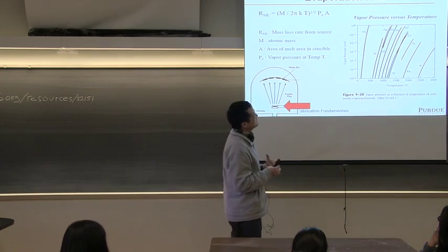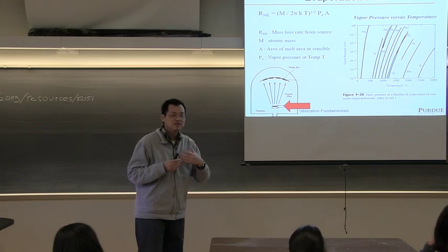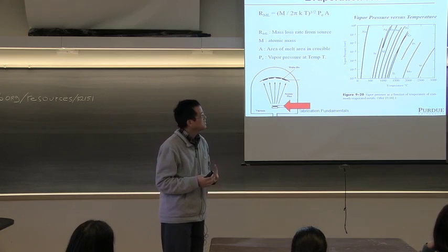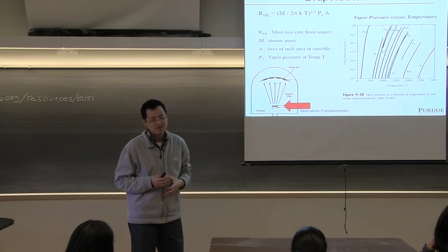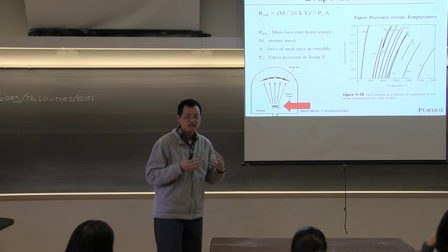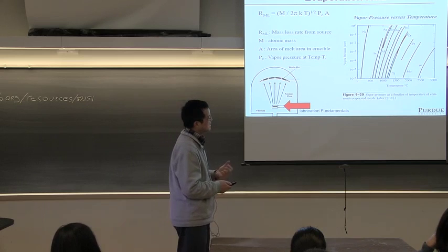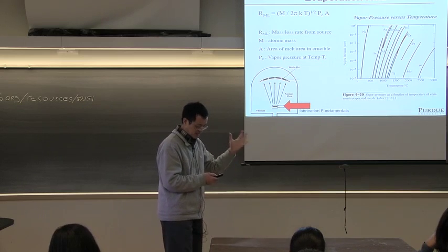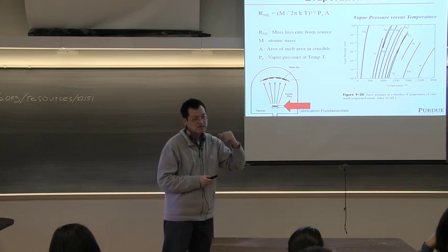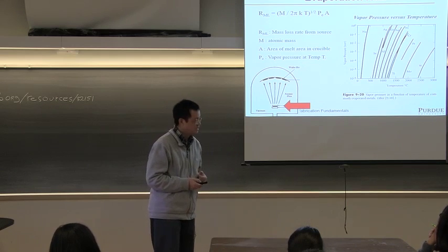So those are some of the metals that are difficult to evaporate, but it's still possible. But this basically raises the question of what if we want tungsten and molybdenum? They turn out to be important metals for integrated circuits or solar cells, for example. So we look at some alternatives, because if you just use evaporation, it's going to be difficult, and it also requires a lot of energy. We'll look at that in the next couple of slides and also the next lecture. For example, tungsten can be done by chemical vapor deposition, and molybdenum can be done by sputtering, etc.